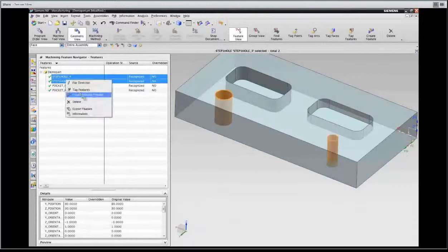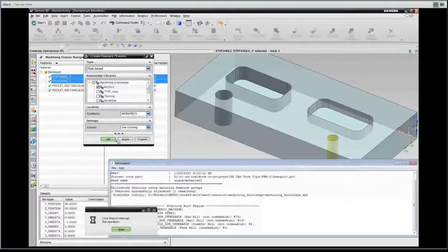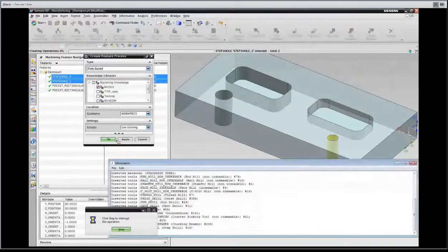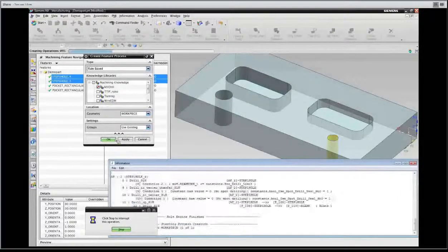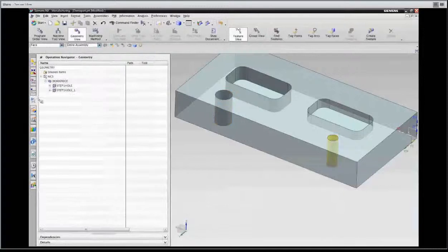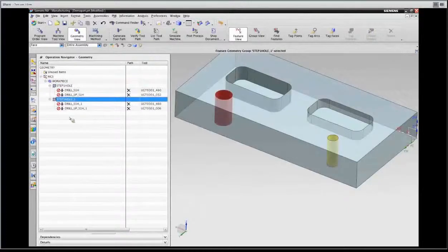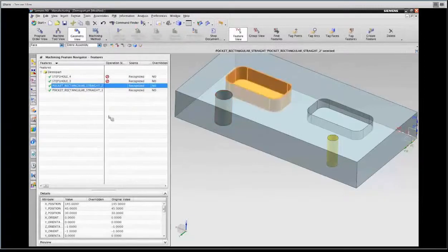And if I just go back and now change the material to stainless steel, run it again, now basically both operations should be big enough. They're both larger than 8, so both need to be pre-drilled. And if I would change it back to copper, one of them would be drilled in a single operation, the other one would be pre-drilled and drilled. Yeah. So the constant mechanism is a way to change out-of-the-box stuff without really defining any new rules. And it's pretty quick and pretty simple.